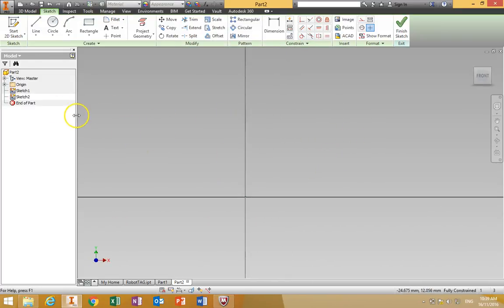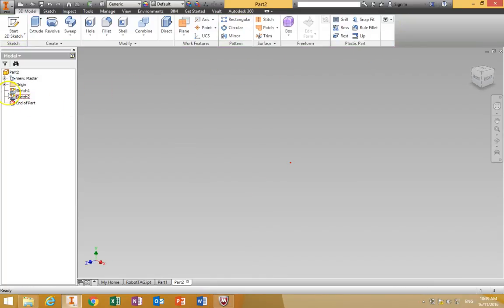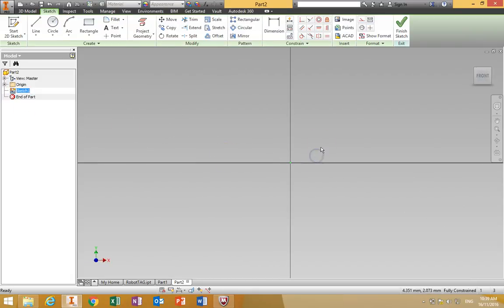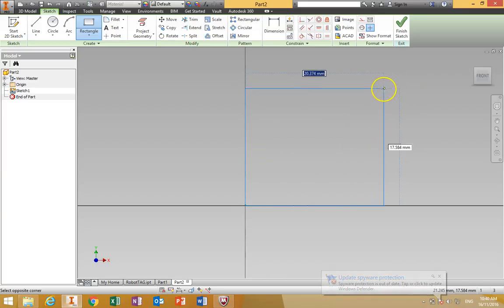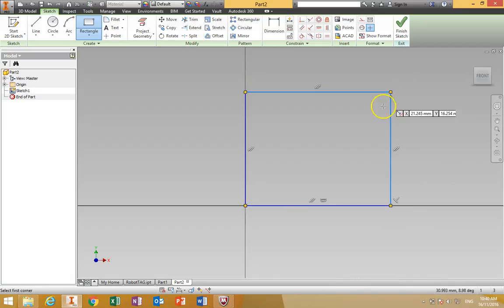So I'll just go back out of this. We've got a new sketch, and I just made two of them accidentally, but we've got a new sketch that you've started here. And again, we're going to press the middle button of the mouse and drag that down and start drawing this dice. And we're going to start the dice with a rectangle. So we're going to start a new rectangle, start on the center point so it locks on. You can see that little green dot goes on top of it, and click once and bring the mouse out here. And the first time we do this, we're going to just make it so it looks like a square. Click the mouse a second time, so we've got a 2-point rectangle.